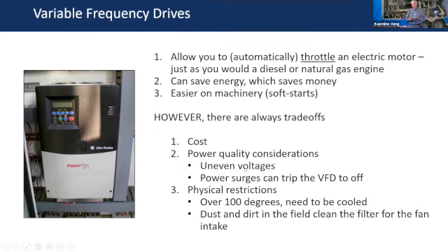There are quite a few different brands out there that are very good. There are power quality considerations. There are uneven voltages off your power lines or through your transformer. Surges can trip the VFD. It can cause problems with your pumping system too.